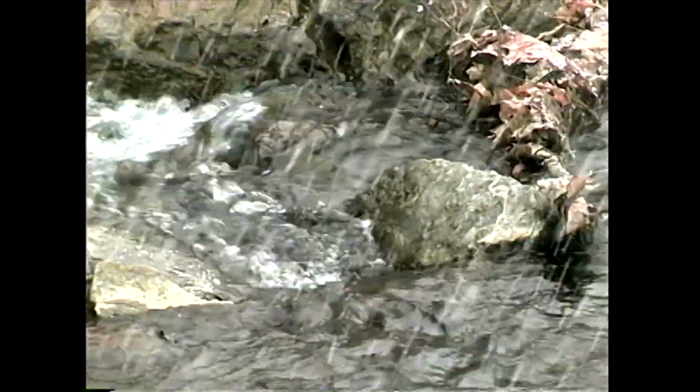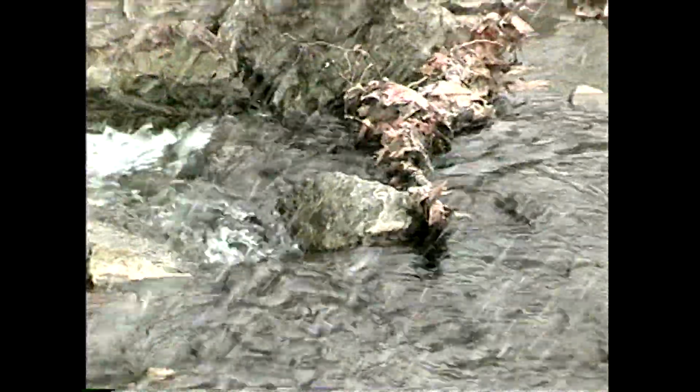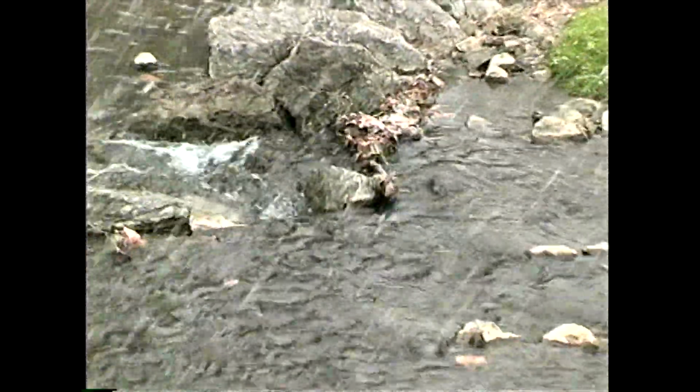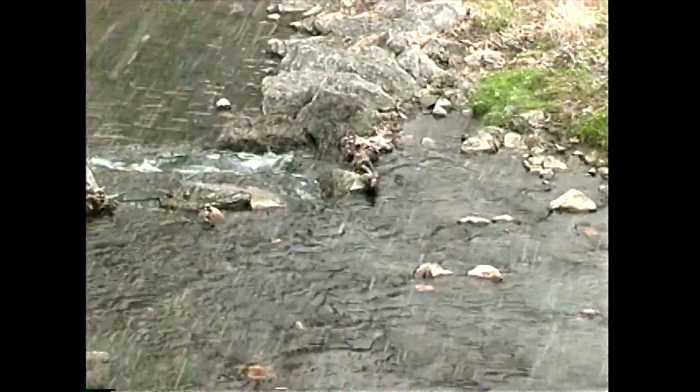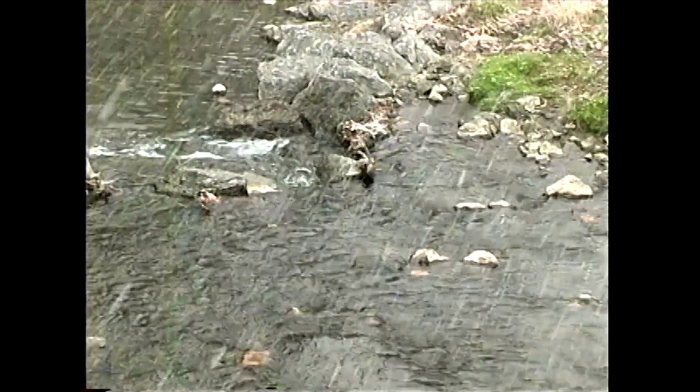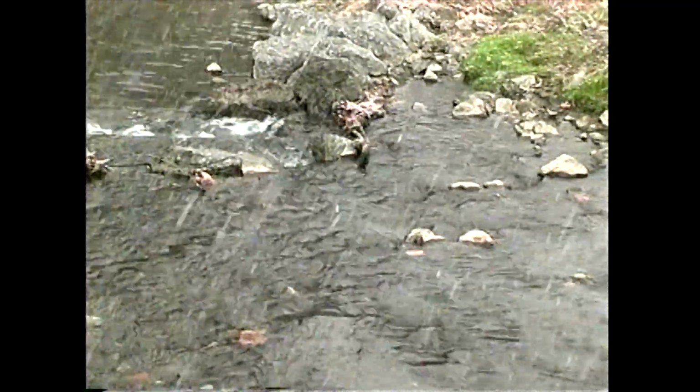And so as the rock vane's legs go out onto the left and right bank, they go up in slope. So during high flow events like flood events, the water has to move uphill there and thus is turned back to the center of the channel.